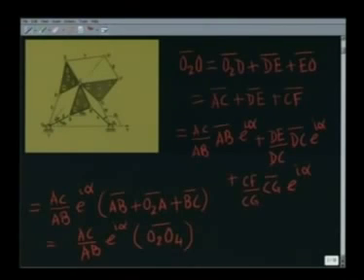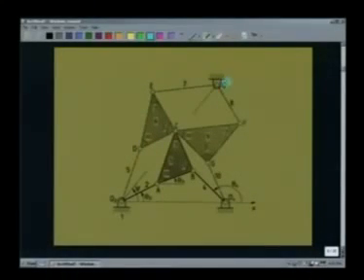So, though this is a single degree of freedom mechanism, all of the other points move as the mechanism moves, but the point O never moves. Just now we have seen that in the 10-link planar mechanism with specific dimensions, there is one point which was not moving, though the overall mechanism had a single degree of freedom. Consequently, if we fix that point O, which was not moving, with the fixed link by putting a hinge, we convert this hinge at O to a higher order hinge connecting three links, namely 1, 7 and 8.